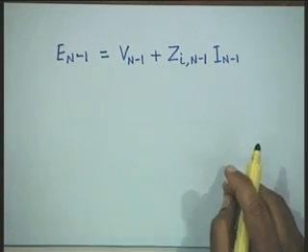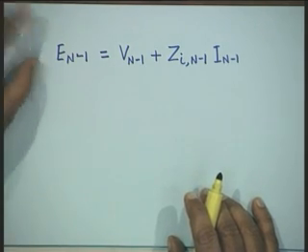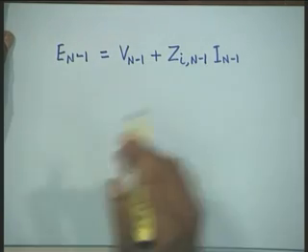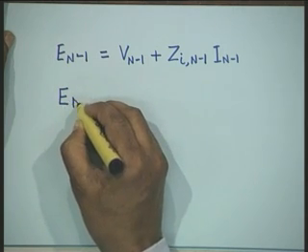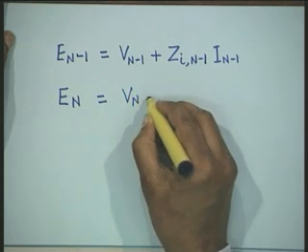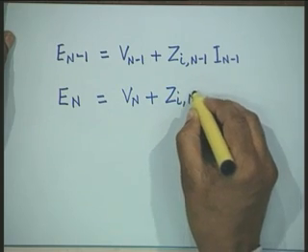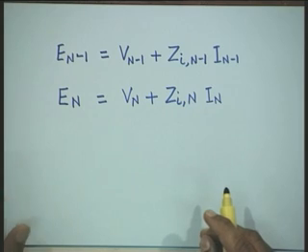That is, let us look, actually that system is not reduced, we actually have the n machines. And then the equation of the classical model looks like this, that the internal voltage is equal to the terminal voltage plus this drop. Similarly, I can write down for the nth machine as V n plus Z I n into I n.